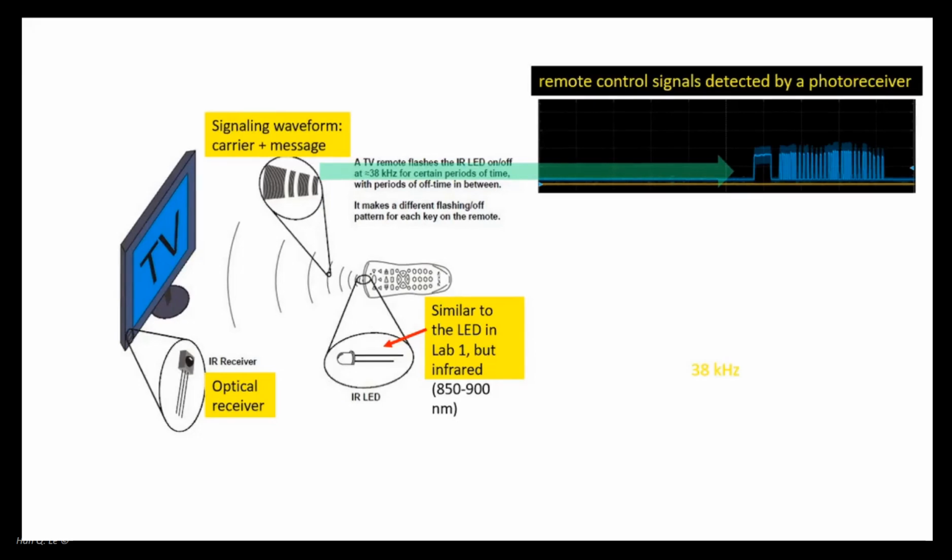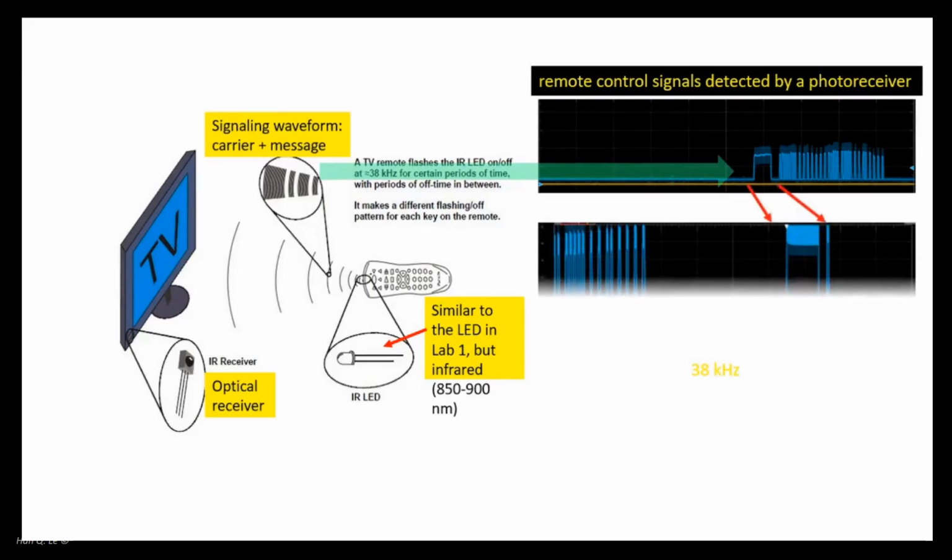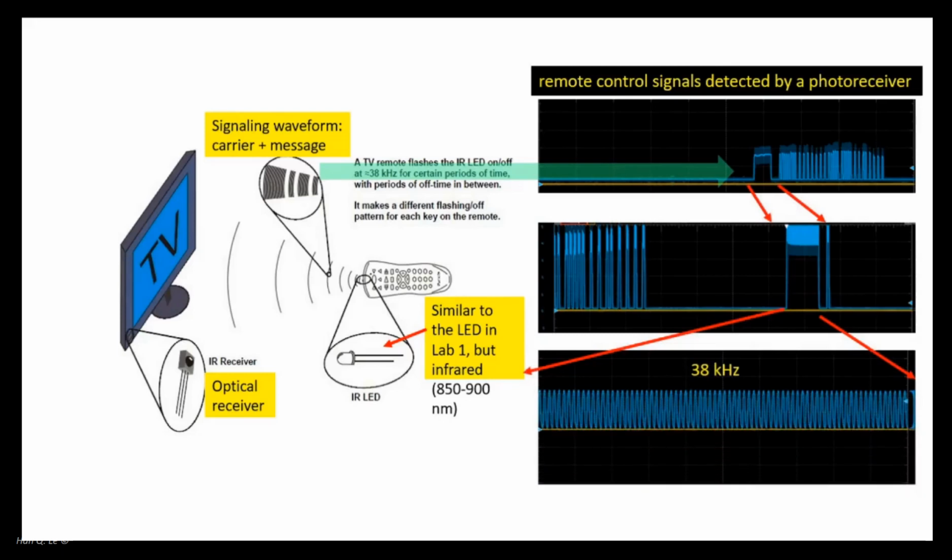In the Lab 4 demonstration, we observe the signal from a remote control. It is a digital message modulated with a carrier frequency around 38 kHz. The need for the high-frequency carrier, as discussed in Lab 6 Part 1 Step 2, is to allow the signal to be distinct from noises and interferences, such as room light, or light from a computer or TV, which do not have that particular fingerprint carrier frequency. The photoreceiver on the appliance tunes to that frequency like a radio tunes to a station. It only listens to the messages sent by the remote, and tunes out everything else.